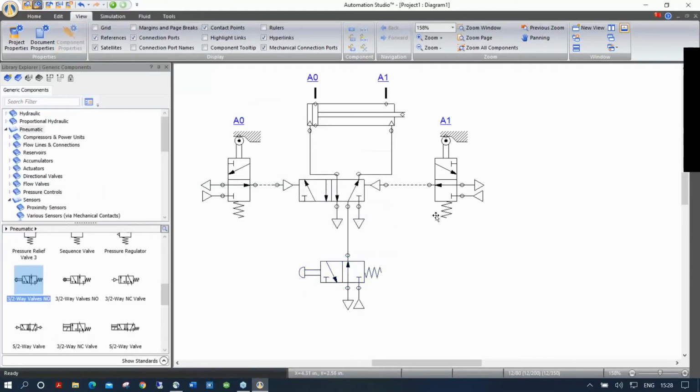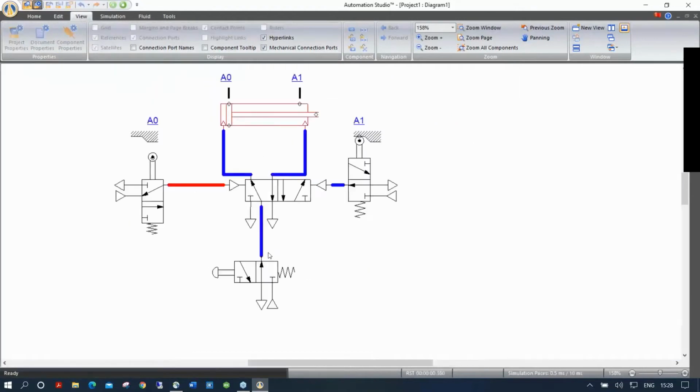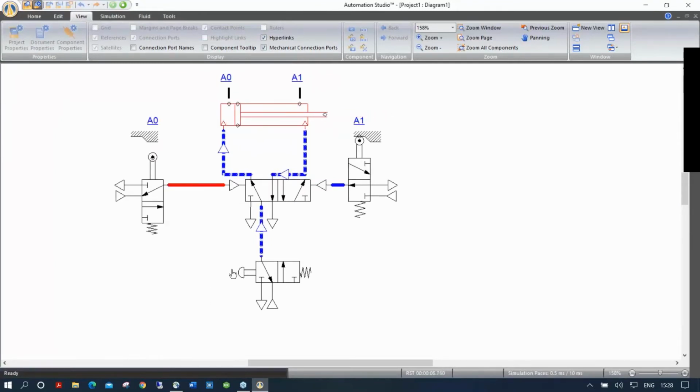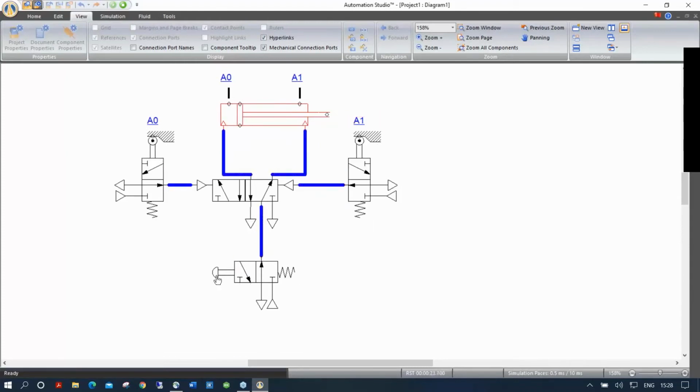Something I did not tell you guys yet is that when I simulate, I have to push this and keep my finger on the button to maintain the push button. If I let go, it retracts, okay? But if you click directly on the spool position, you will lock that spool position in place, okay? And the only way to remove that forcing is clicking on one of the two commands. If I click on the spring or here, it's going to take it off. You see, if the hook is here, if I click on the spring, it goes away.